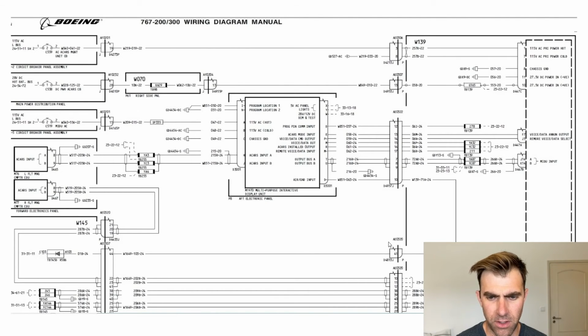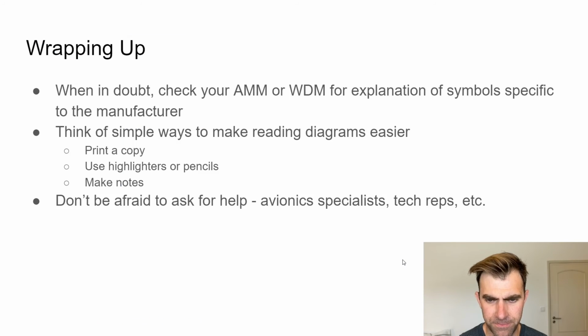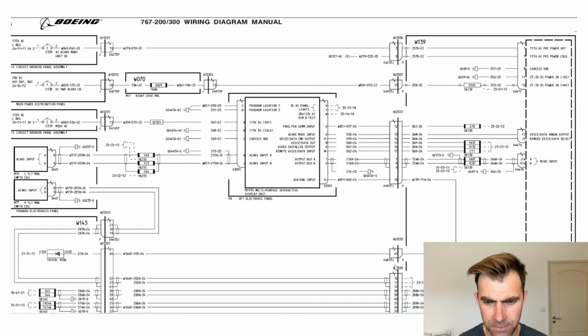going to have a connector identifier label, just to make sure that you know where it's located, and so that you can track it down on the wiring diagram. And you'll see a J and a P side. That just denotes the different side of the connector.